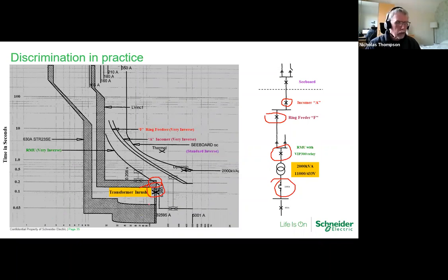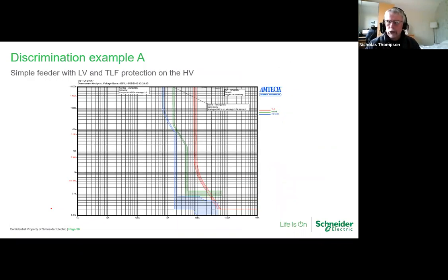So when you switch a transformer on from cold, you're energizing the core, so therefore you get a very high inrush of current, anything between 10 and 20 times your normal full load current. That will be for a period of time, and then it will drop off. So you need to be mindful of where your inrush current is going to be, otherwise you could end up with nuisance tripping.